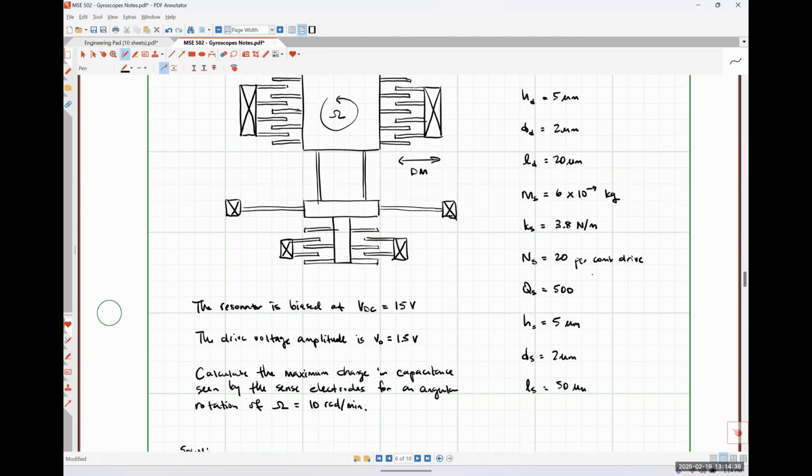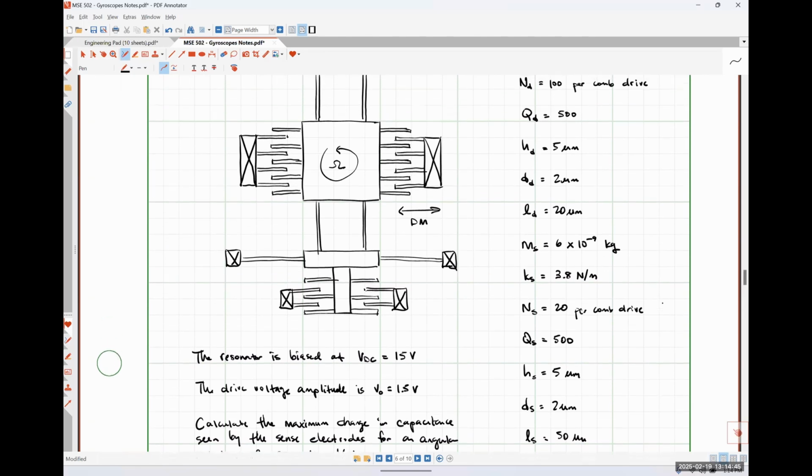All right, so I need to make a fix here because North caught something and it actually breaks everything. So good catch there. This QD needs to be 50. Let me explain why QD needs to be 50. If it isn't, our displacement is larger than the actual length of our electrodes, which isn't going to work. We're going to smash into the sides of this thing.